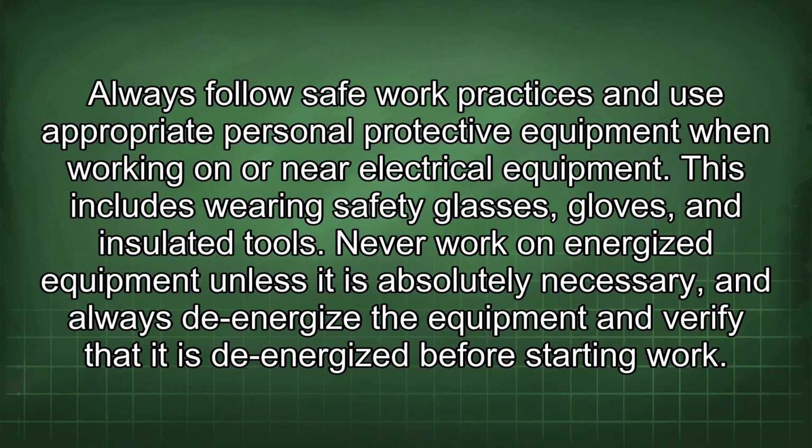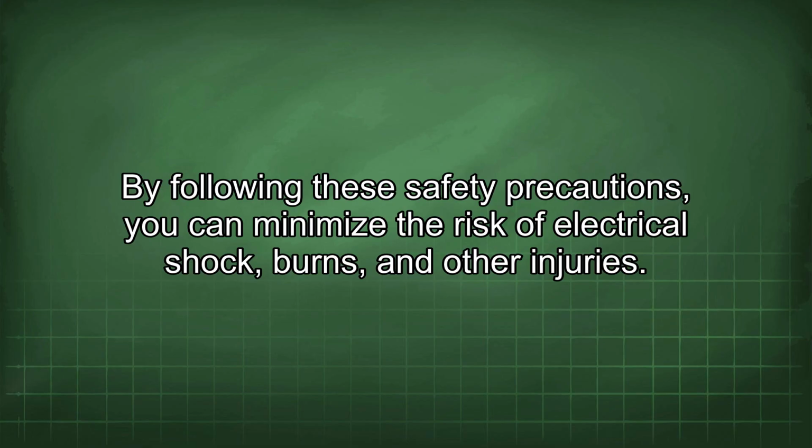Never work on energized equipment unless it is absolutely necessary, and always de-energize the equipment and verify that it is de-energized before starting work. By following these safety precautions, you can minimize the risk of electrical shock, burns, and other injuries.